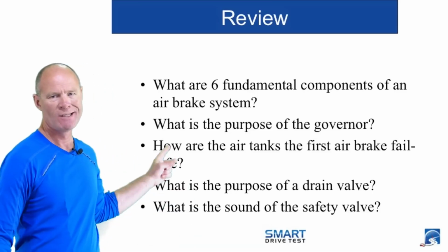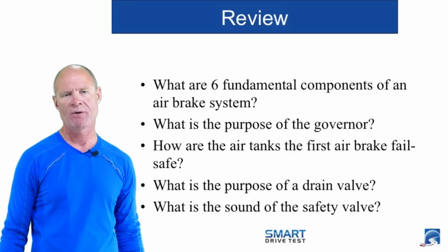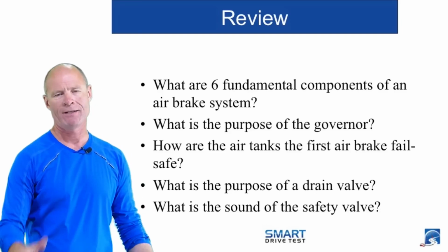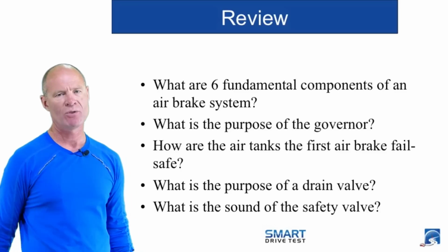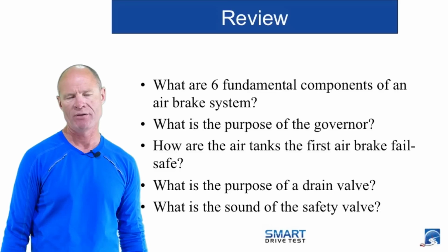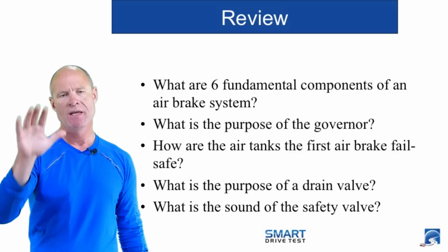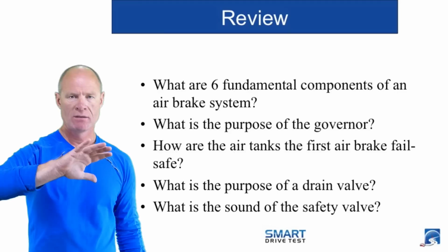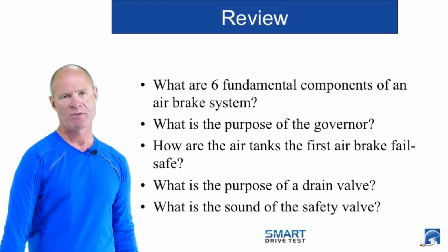And the last question: what is the sound of the safety valve when it blows off at 150 pounds per square inch? The sound is a machine gun. That is the sound of the safety valve blowing off excess air in the system, because if you have too much air, you could cause damage to the system and potentially to yourself or other people around the vehicle. So all tanks used in industry and for commercial uses have a safety valve that blows off excess air or vacuum; the purpose of the safety valve is to prevent the tank from either exploding or imploding.